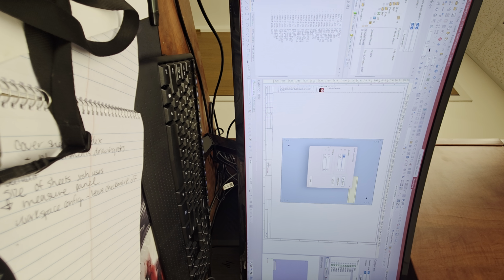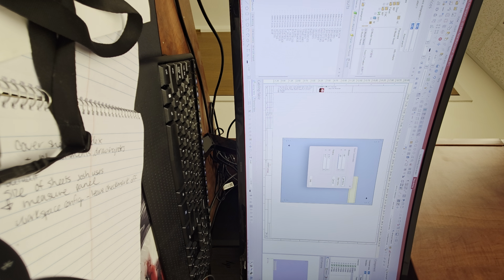So now you have this little prompt where you have absolute positioning and relative positioning. So absolute positioning, for example, right now you have 10 inches from your left, 9.625, which was our approximate placement. So you can adjust this to be your 10 inches. And the X one on the top, if you see the ruler all the way on top of your screen, that is your 80 inches ruler as a place in space. Again, why it's 80 inches right now, I think our initial placement probably on our sheet was not at 0, 0 when we started.